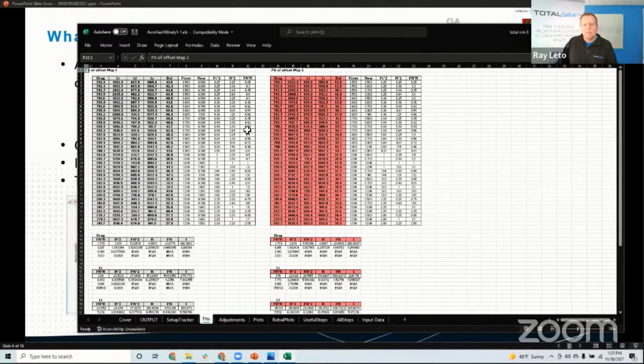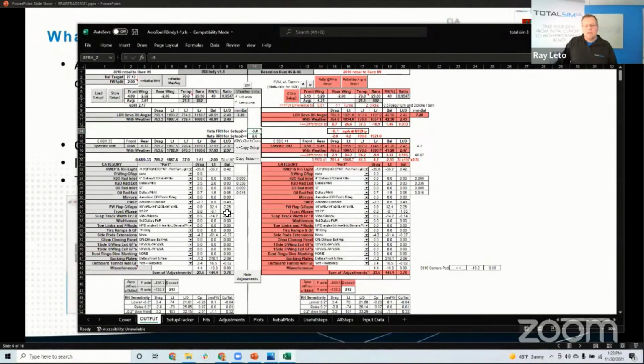We've got these data tables. For every ride height, we've created a lift, drag, balance. We can take that and input it into lap simulation like Danny was talking about yesterday. It can be used on a driver in the loop simulator, or it can just be used like in this case, this is an old setup tool that I had where we're comparing one setup to another.